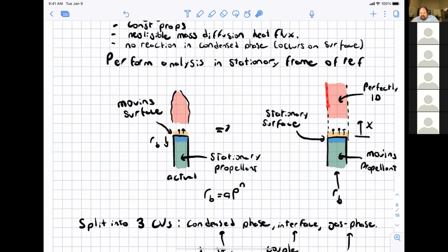And now we are integrating the gas phase flame structure, and what we're going to find for that is a relationship for the gas phase heat flux. So now we are finding the structure of the flame in the gas, the structure of the temperature in the condensed phase, and we are using an interfacial energy balance to connect those two.